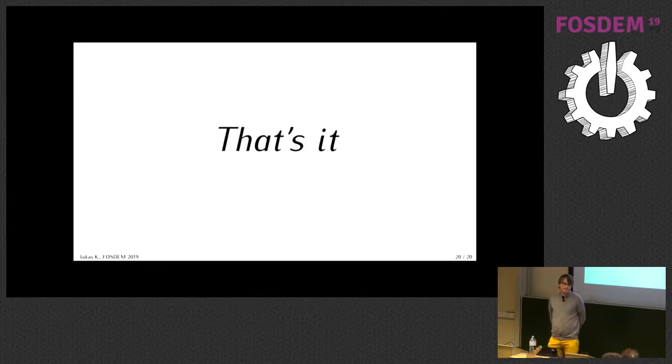Yeah. The question was whether there's a way to specify generic parts, since the pool should only contain orderable parts. Octopart has the Common Parts Library, the CPL, and in there they have a naming scheme for passives, like a CPL 1K or 603 0.1 watt, and I already imported these into the pool. If you happen to use Octopart for your BOM generation, then Octopart will resolve these into an orderable part.